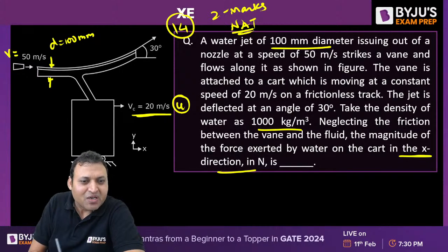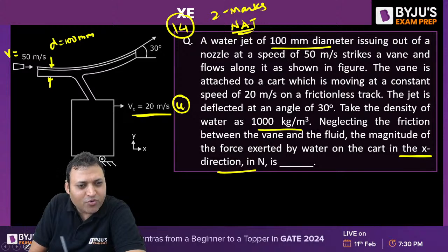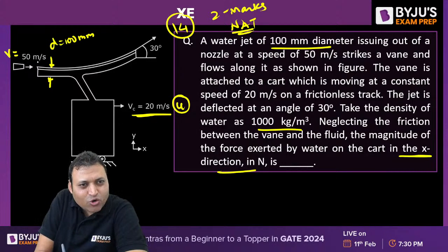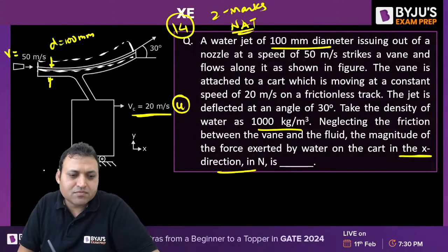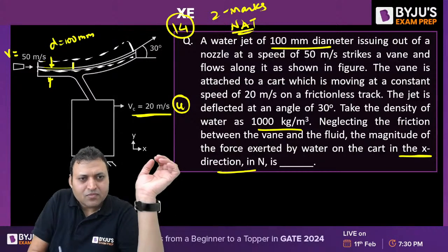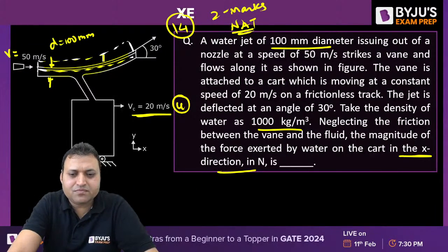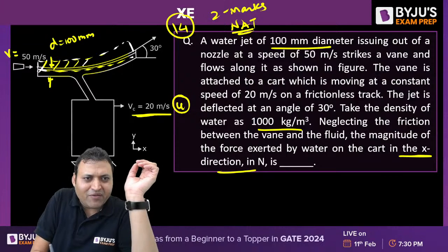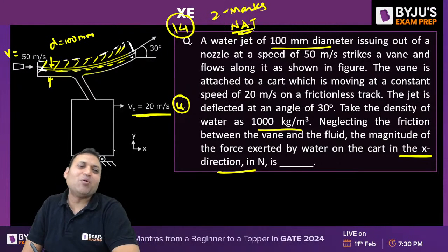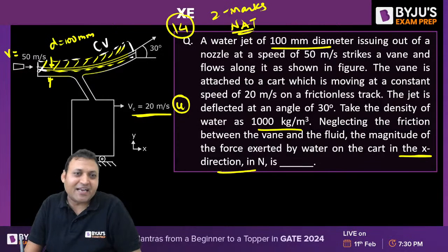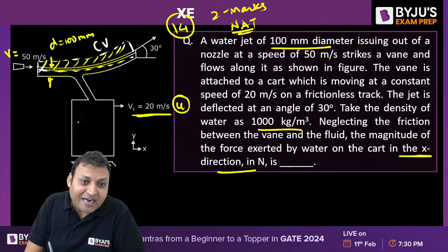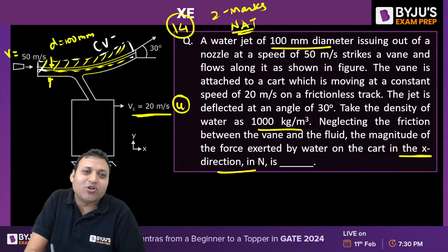That is for sure. So if we talk about this control volume, this is our control volume, let us say. And we are going to apply the momentum equation in X direction because we need to find out the force exerted in X direction. But because the cart is moving, the control volume is also moving.